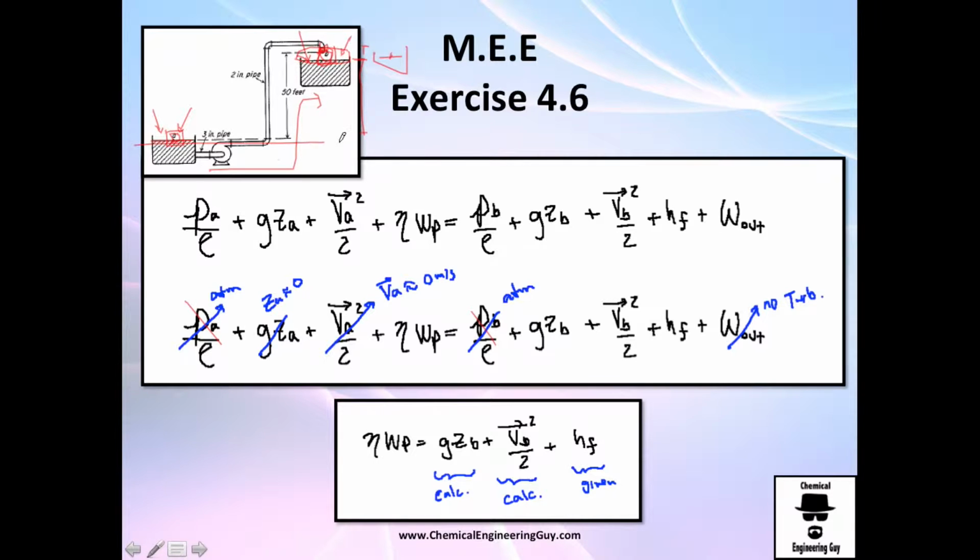I want to choose the reference point here, 0, because as you can see, these 15 feet are referenced to point A. So we could say the height at A is 0, so this converts mathematically to 0. What else do we have here? Since this is at rest, we could say the velocity is almost 0. We cannot cancel the pump because we want to calculate the pump. Actually, this is 50 feet. The velocity in B, we don't know it actually. You just know, of course, that it goes away with some velocity.